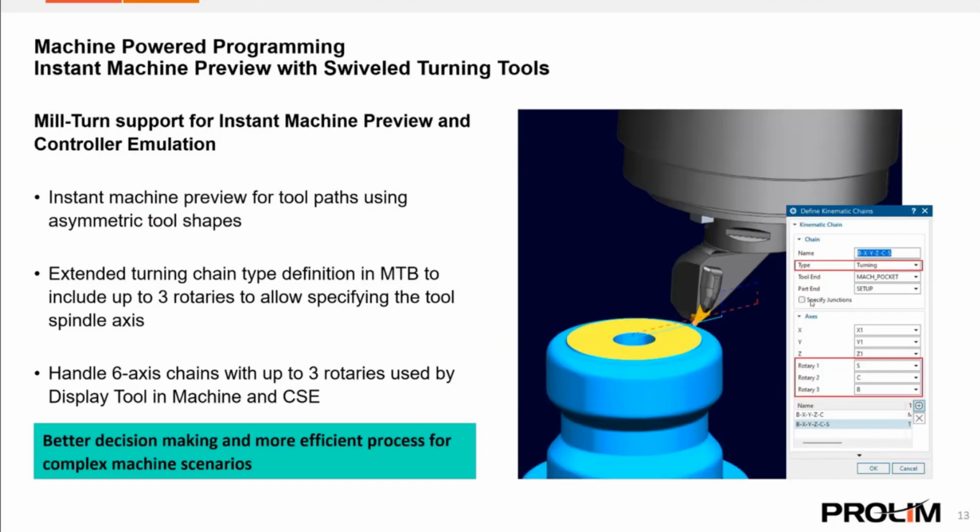And the other enhancement in machine powered programming is instant machine preview with swivel turning tools. Pick on path with machine provides the user an easy way to see and manipulate the machine axis outside the simulation task environment in the CAM context. So it is lightweight and can be used at any location on a toolpath. Usually the simulation environments need a lot of RAM to play all those IPWs and so on, but with this option it's much easier, and it's right away, within a few clicks.